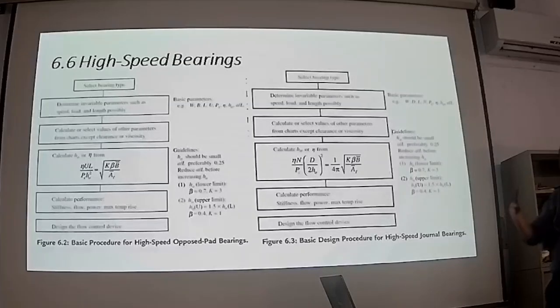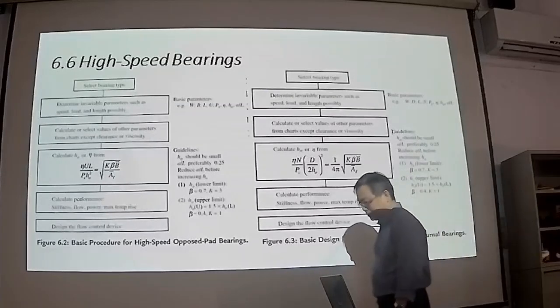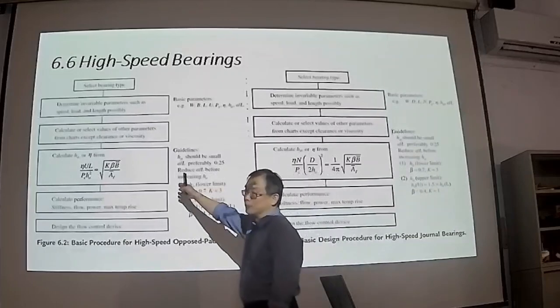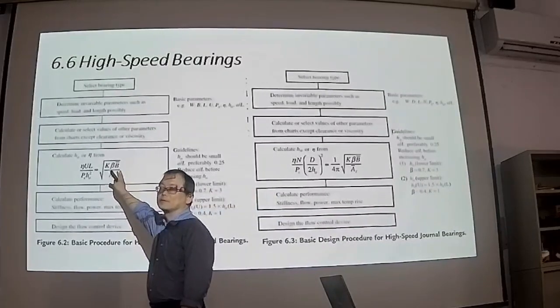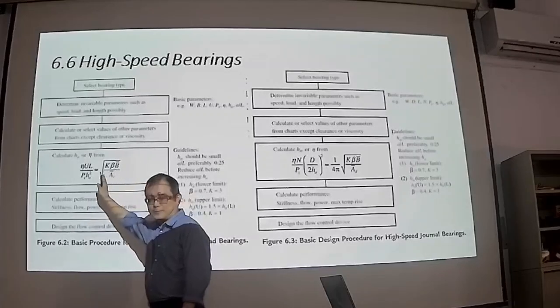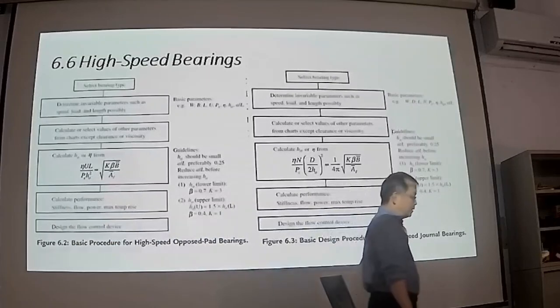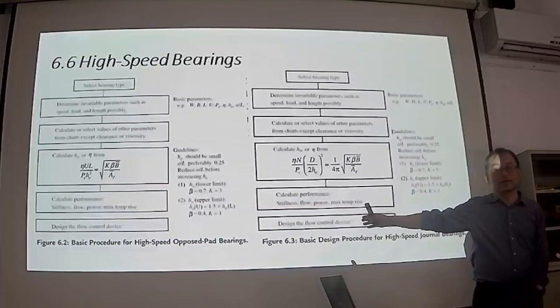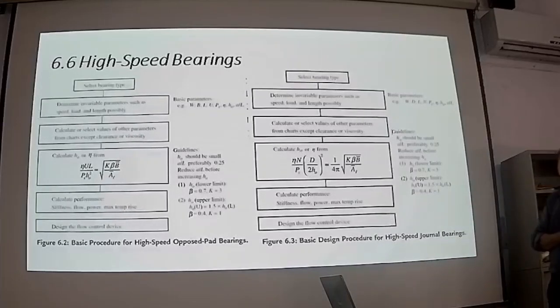Then you can make some reference from the commercial product on the market, and then you will know what kind of lubricant they are choosing. Okay, so you can use that as your viscosity grade of lubricant, and you use that viscosity number for some estimation. So if it fulfills your requirement, then you can use that one. Okay.